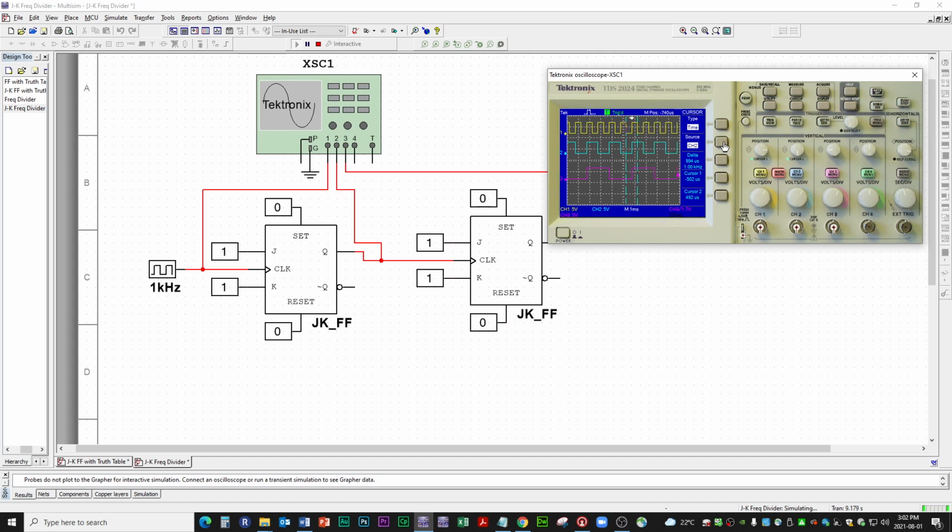So let's click that, channel 2, no, channel 3, there we go. We have those 2 magenta cursors appearing, and these 2 controls are going to move the left and right cursor. So let's bring it up to where 1 begins, here. It's tough to get it right on the spot. Ah, there we go. I think we got it right here where it begins, and get the other one when it starts going up. There we go. I think I got it.